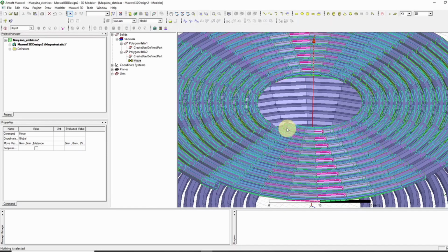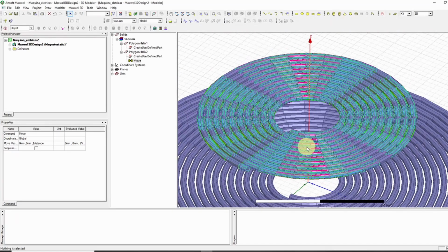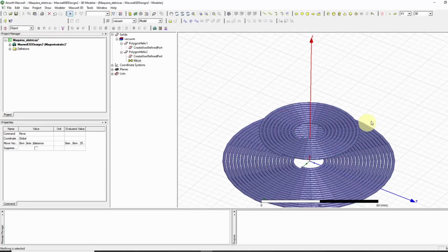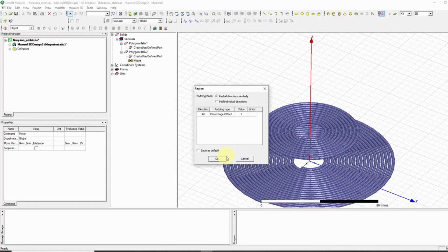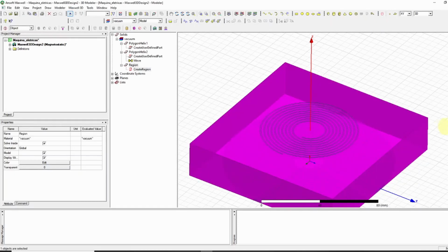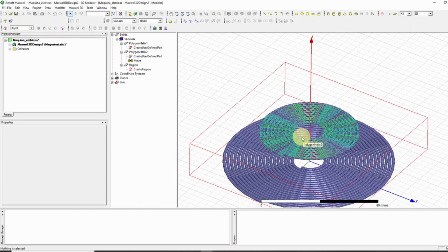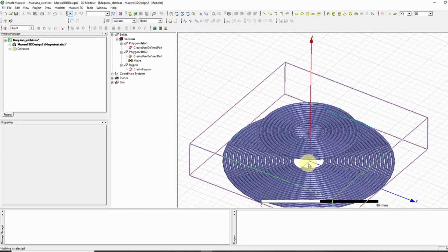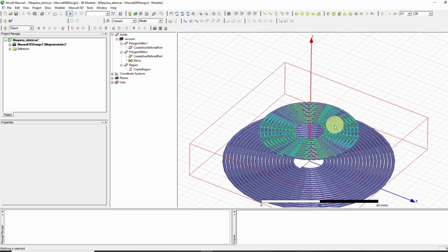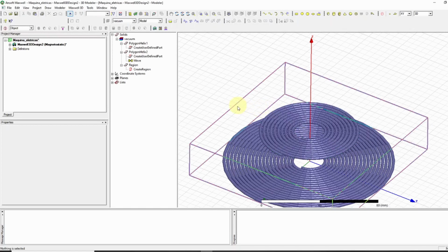You see there's an end here to the boundary. It's impossible without a conduction path. I'm going to show you right now why it's impossible. So creating a region here, just as an example, is going to touch every single outside face of it. And you see, the region is not touching the faces inside of the place in which I want to have one of the wires. We need to have a conduction path in order for this wire here to touch this region. So let's do that right now.